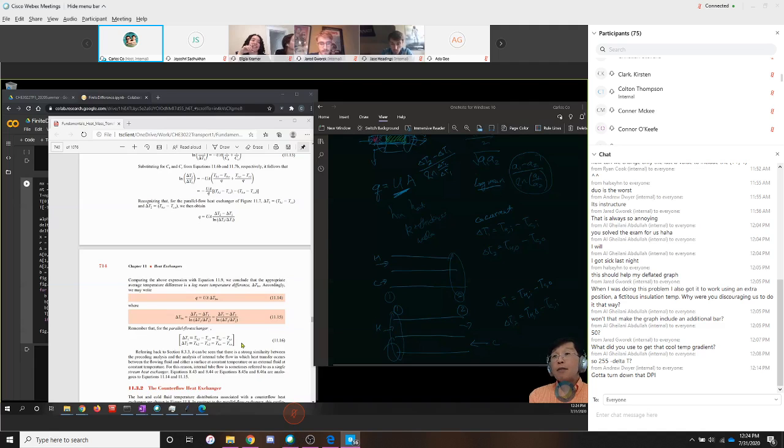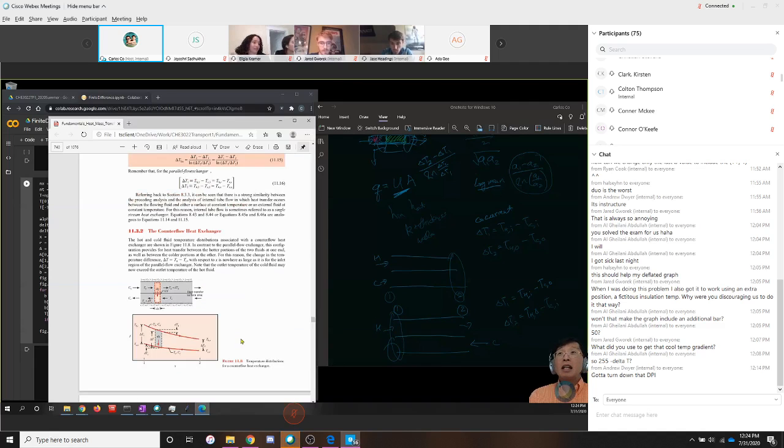So now you might ask, well, at the start of this class, I made a big fuss about how one is better than the other, right? Okay, so let's think about it this way. So this might be how the counterflow heat exchangers work. Notice that if you have it going counterflow, your hot stream goes down in temperature. The temperature of the cold stream that comes in is entirely at your control. You can set whatever temperature is going to go in there. That's the inlet temperature of the cold stream. The outlet temperature, of course, will have to come from an energy balance, right?